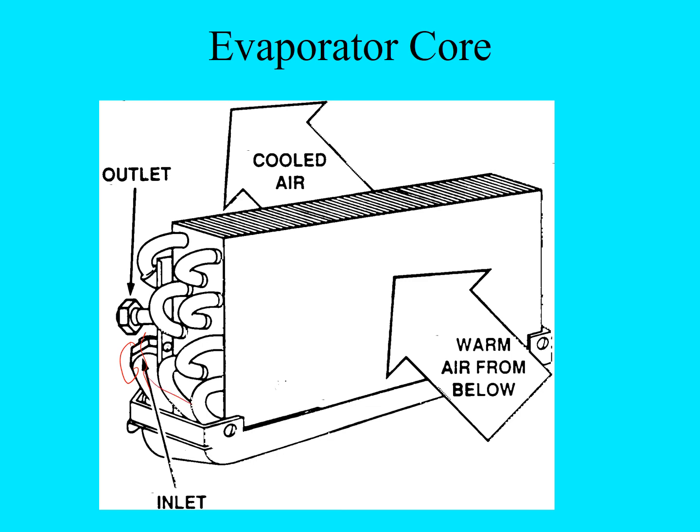And warm air is flowing through this, and because of that, it's going to get the temperature change to take place that the liquid refrigerant needs, so it will vaporize all into a vapor and leave the evaporator core out the outlet as vapor. So this is where the liquid refrigerant vaporizes: low temperature, low pressure liquid changes into a low temperature, low pressure vapor.